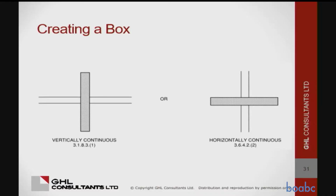So, when we create this box, it's either vertically continuous, meaning the vertical fire separation continues through the concealed space in the floor or the roof, or it's horizontally continuous, meaning the fire separation abuts up to a horizontal fire separation, and then you've got all these boxes, basically.